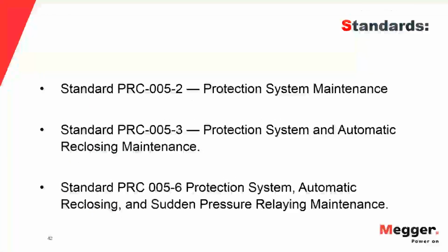Now, the other reason: NERC requires that you test reclosers. There are several documents from NERC that tell you how often you have to test reclosers, what the recommended tests are, whether it's going to be a time-based maintenance schedule, and what the frequencies are and things like that.